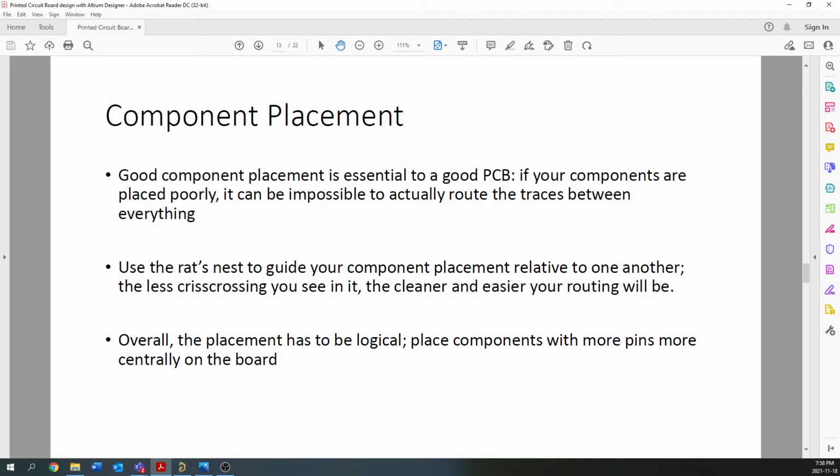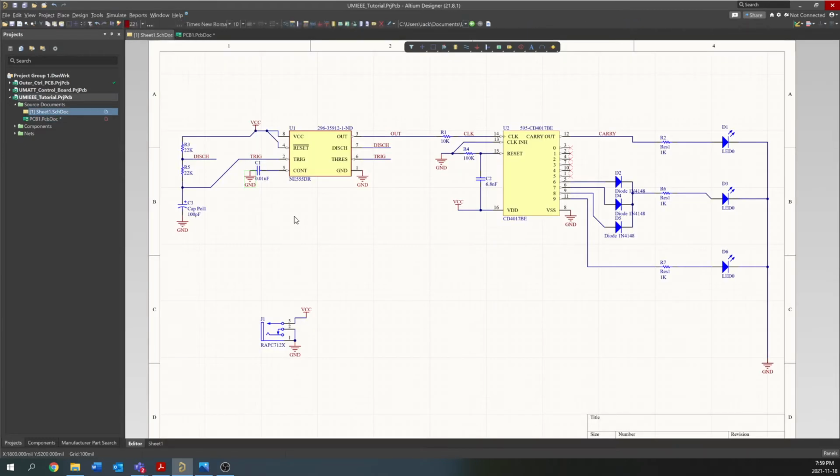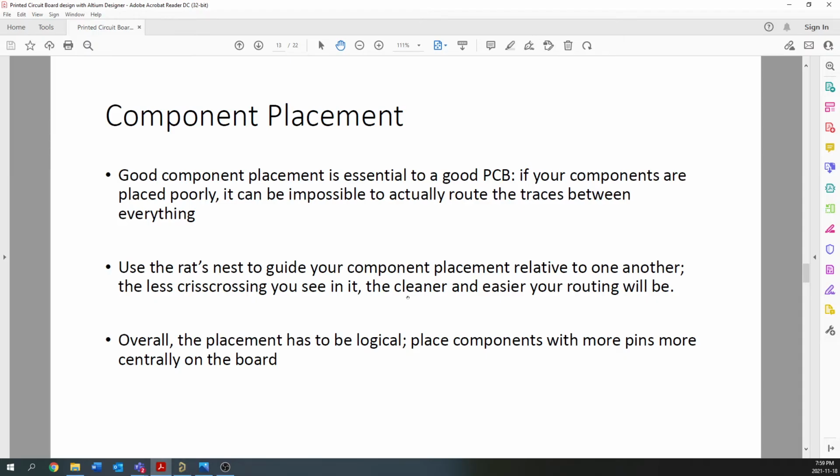In general, if your board allows it, you could even lay out your components in a similar manner to how your schematic is. Unfortunately, the schematic symbols that you get are not the same as the actual component footprints, and moreover, you can't just use a net and a net label to bridge, for example here, discharge and bring it over here and have an imaginary wireless transmission between these two. That, of course, does not work in the real world. So we need to physically connect those nets, and I'll show you how to do that here.